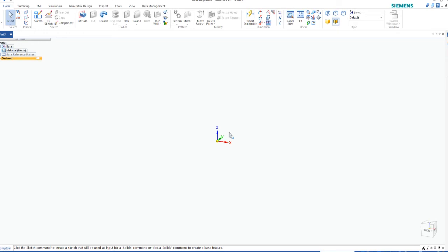This part itself is primarily cylindrical. There are very few straight sections. It's nicely shown in front view and also using the section view. We're going to be gleaning the majority of our dimensions from both views. Primarily the section view is going to give us our main linear dimensions, as well as our refining dimensions for our filleting and also the overall size of the dome.